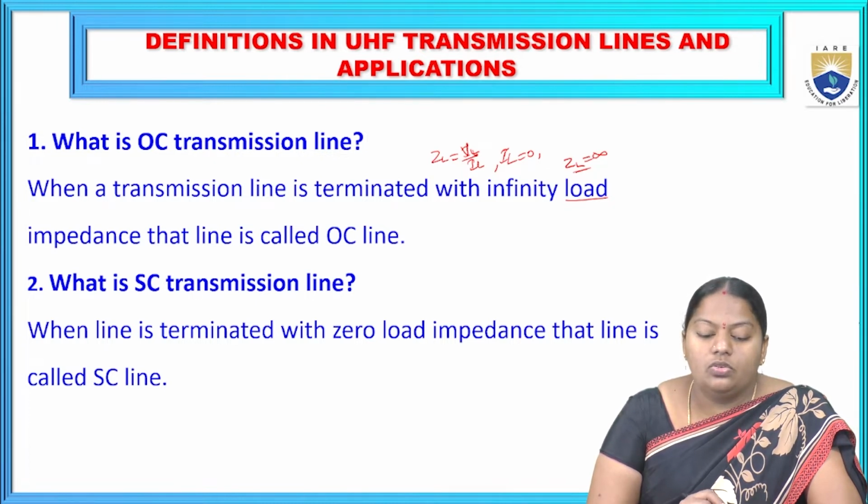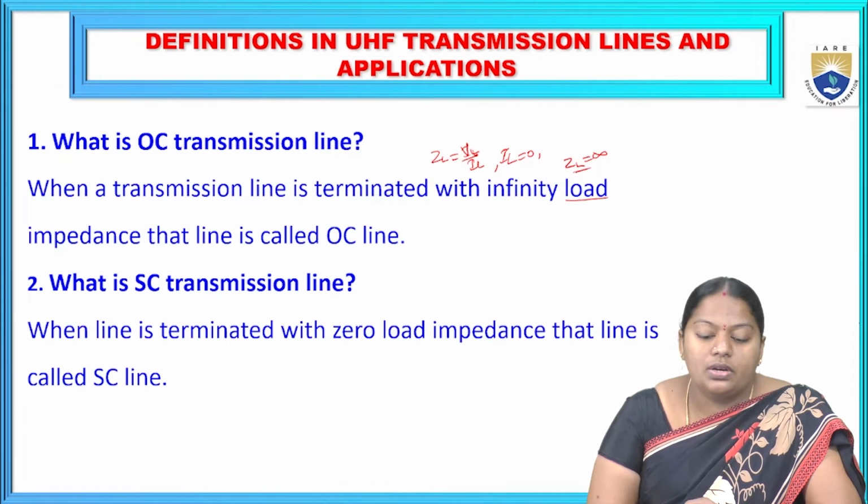In order to know the open circuited and short circuited transmission lines, we use the notation Zin for the input impedance of a high frequency transmission line. In that, we substitute ZL by 0, or sometimes ZL by infinity, to obtain the short circuited or open circuited impedance.